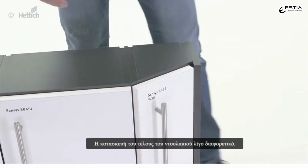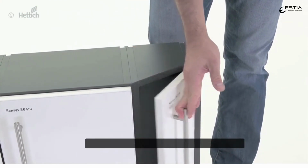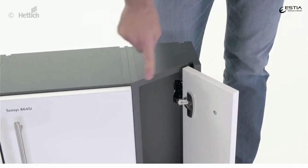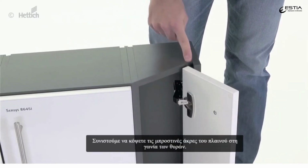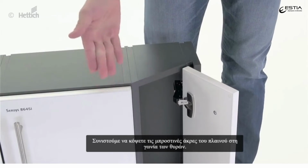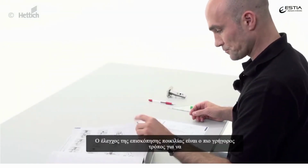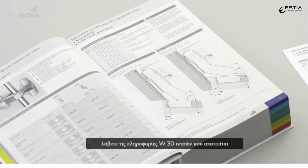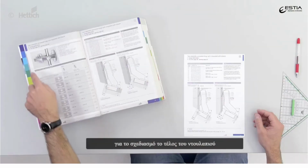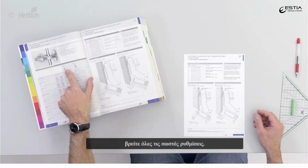The construction of the end cabinet is a little different. First of all, the cabinet requires different side panel depths. In order to create a perfect design, we recommend to cut the front edges of the side panel in the angle of the doors. Checking the assortment overview is the quickest way to get the W30 hinge information, which is required to design the end cabinets. The catalog documentation helps to find all the correct settings.